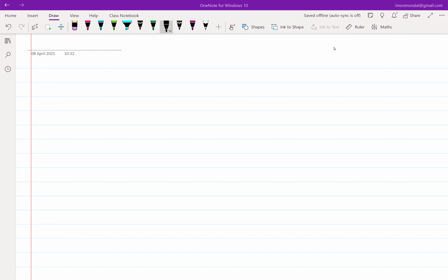So let's start off with the receiver topology and then show how a transmitter is similar or dissimilar to a receiver. You have a receiver where you maybe have a SAW filter, then you have an LNA, then let's say you have image reject.